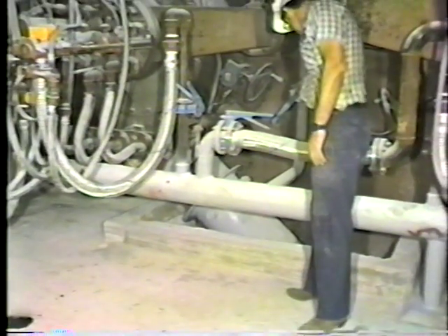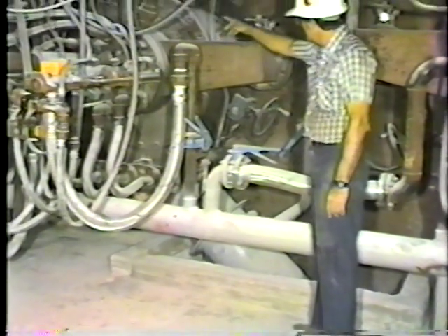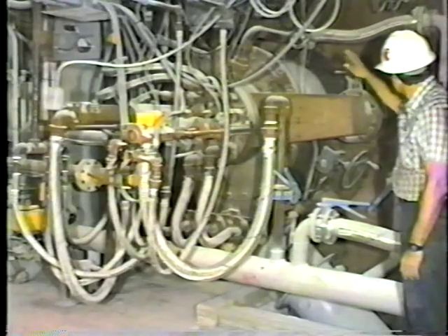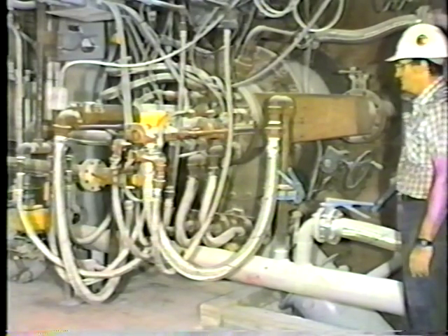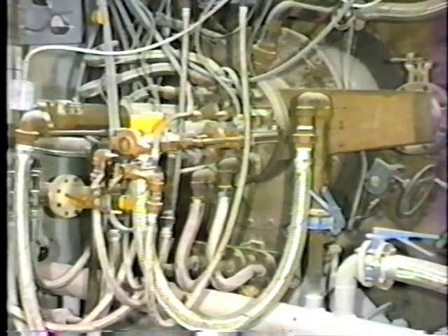This Foster Wheeler burner is equipped for coal, number 6 oil, and gas fuels. Reducing the turbulence in the inner annular region nearest the fuel while directing the major portion of the air to the outer annulus lowers the flame temperature and NOx. The back wall of the burner where the burners are located.